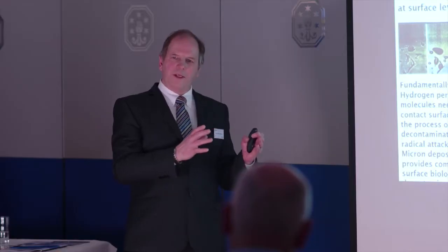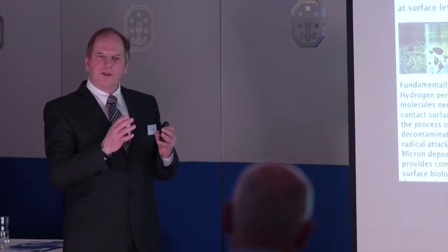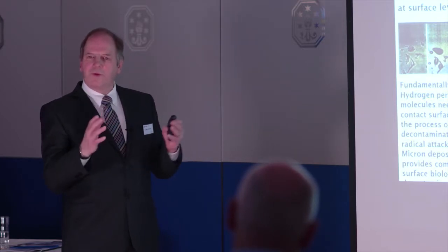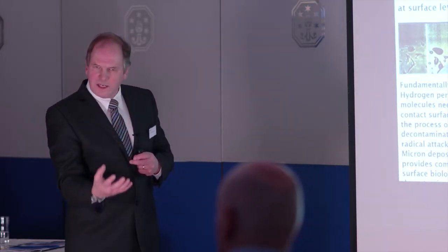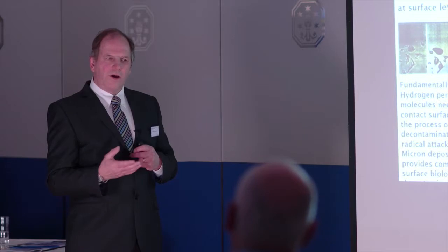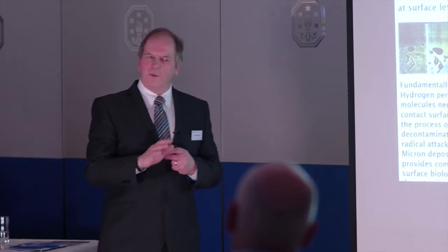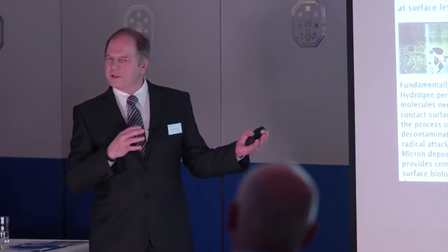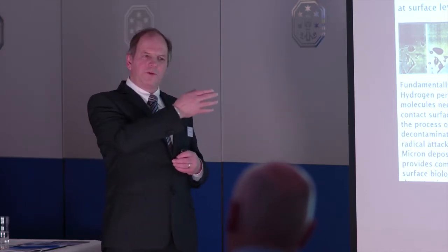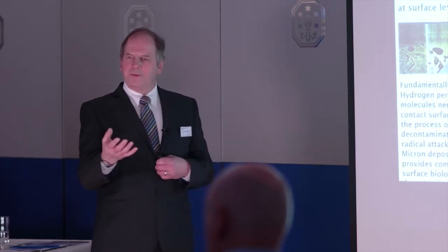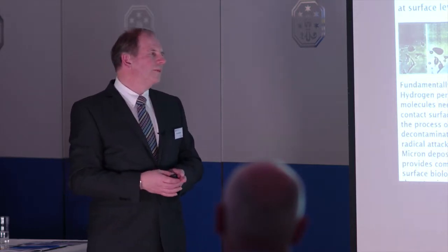When you flash evaporate, you get whatever the concentration is off the vaporizer. The vapor pressures take predominance. So when it gets into the isolator volume, peroxide starts to condense first. Primarily you get a higher surface condensate, up to 70%, and that's a real kick for kill. Now when you get into equilibrium, which happens quite shortly thereafter, if you started with 35% concentration, the equilibrium is 35% concentration. The condensate on the surface is 35%. That's the equilibrium state.